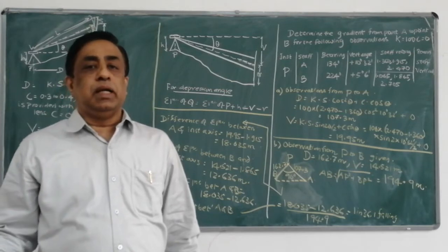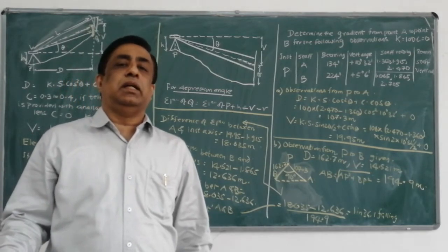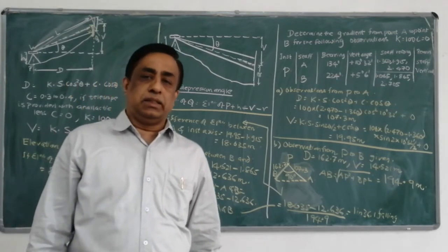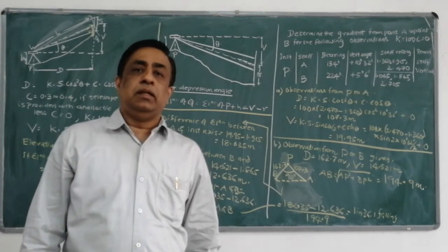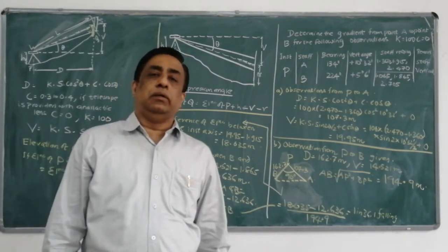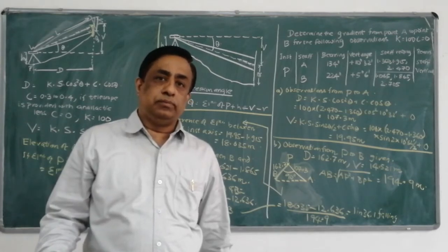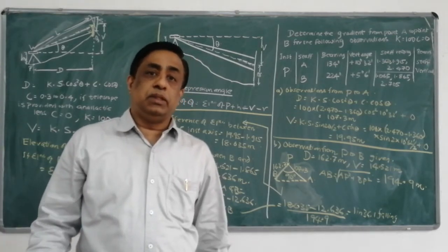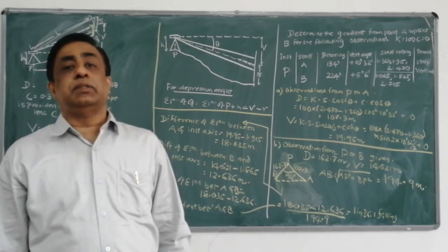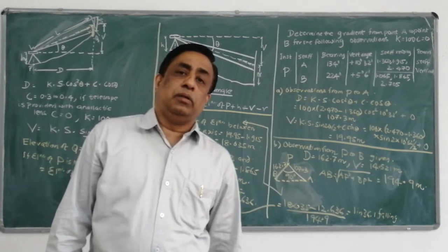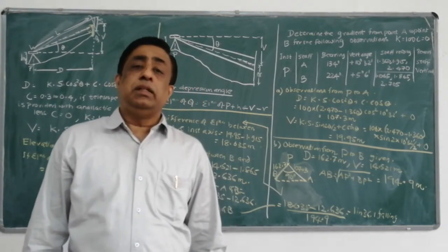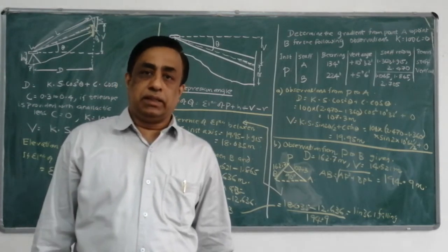That's why a tachometric survey will be utilized for smaller areas only, for smaller area topographical map preparation, and also for preparation of engineering maps which are needed for your route alignment as well as for your pipeline alignment laying. These are our civil engineering applications.